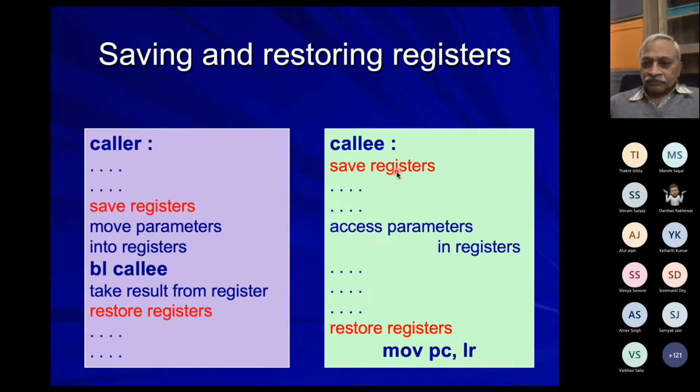Sir, so the stack is present in the memory, right? Yeah, there is no fixed stack as such. In memory, anywhere you can create. So you initialize the stack pointer to some memory location, and then the stack starts building from that point onward. So there is no hardware stack, so to say. The programmer has to manage a stack in the memory itself.